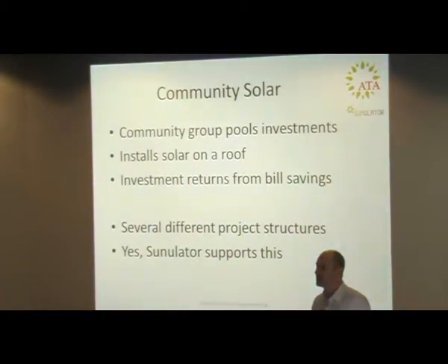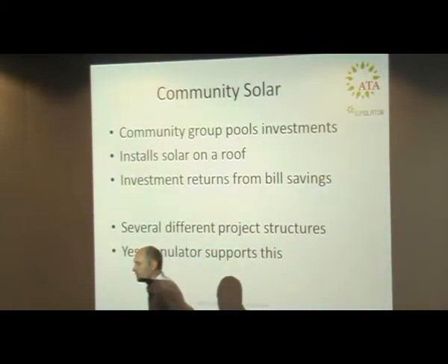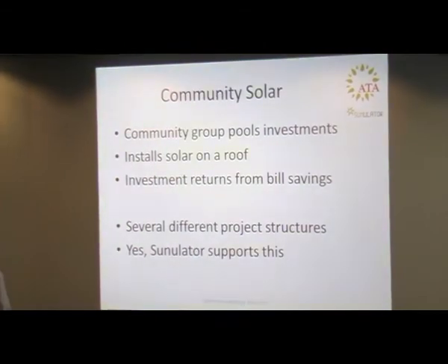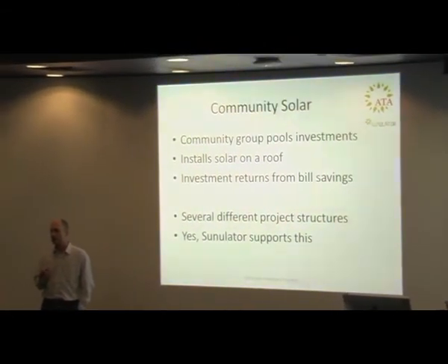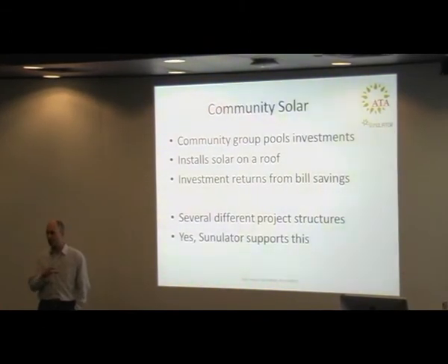Probably the main limit is the rebates for the renewable energy. Sorry? With us, most of it will be consumed on site. But no, in terms of the modelling, is there an upper limit in terms of the size of the... In terms of the modelling? Simulation. No, simulation, no. But if you go greater than 99 kilowatts, then you can't claim your small technology certificate rebates up front. The only way you can get any carbon value for it is by trading on the market, which is problematic at the moment. I think most of what we would hope to generate would be used on site. Yeah. And generally we're talking about common area and facilities being covered, not the entire residential unit system.